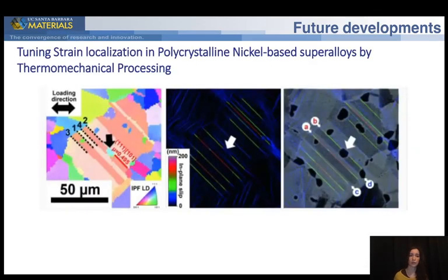And to do so, we introduced second phase particles on the twin boundaries so that we don't have long and large twin boundaries anymore, and those particles, which are shown here in black, actually block dislocation motion. They better resist dislocation motion, and so we observed that strain localization is greatly reduced in a local and overall manner in the engineered microstructure.